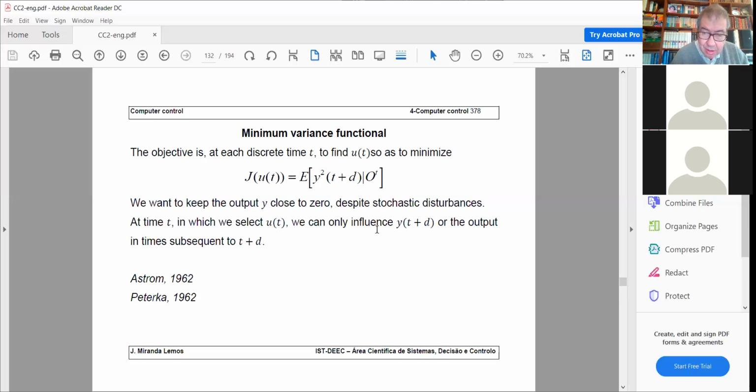in the other case, the control law that you are using in the lab, you are considering an infinite horizon. Okay, so that minimizes the power of your output. You always refer to the state. So remember that you can write y as cx. So instead of having y squared, you write x transposed c transpose c, which is a matrix, times c times x. But that's immaterial.